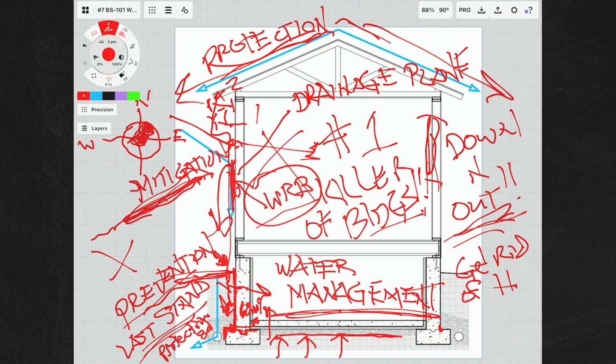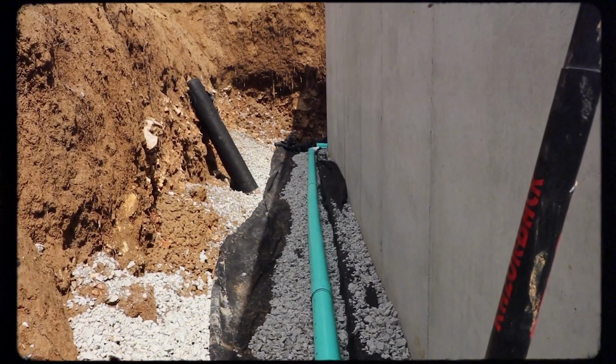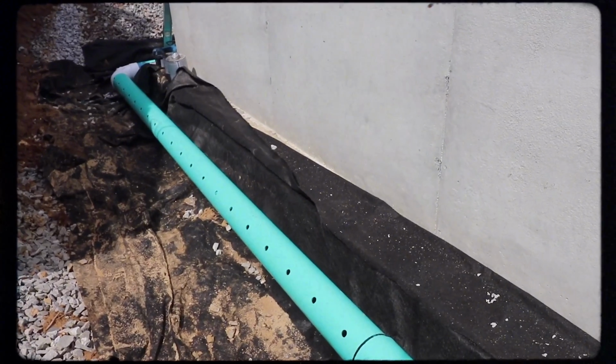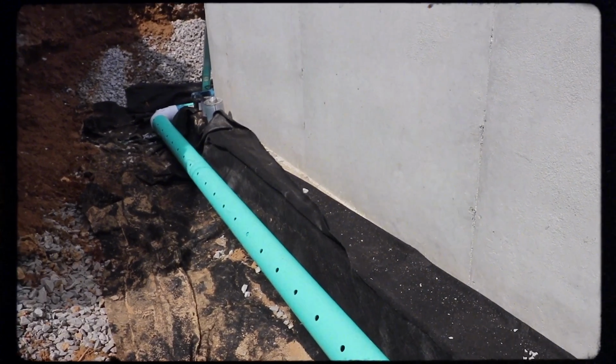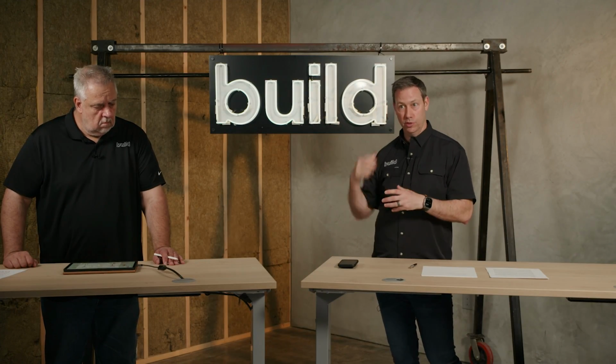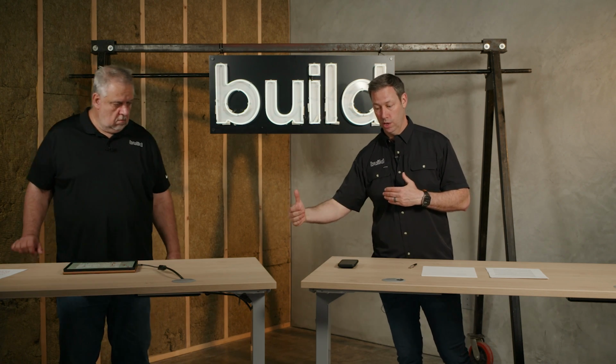So water that gets down there is going to have a hollow tube that's connected to a low point, a sump pit, and the sump pit has a sump pump in there, which actually pumps that water out, assuming that it's not a place to daylight it to go below with gravity feeding to go out.